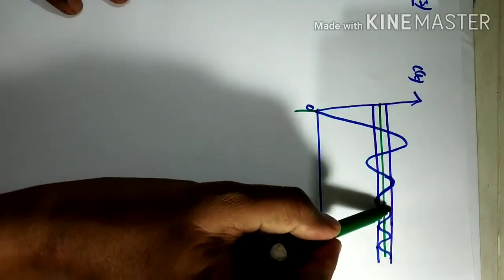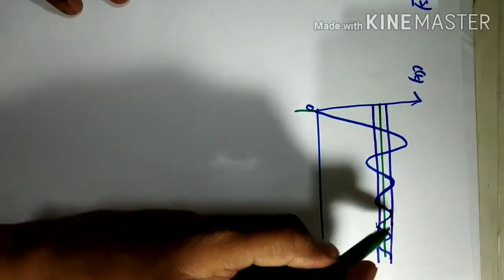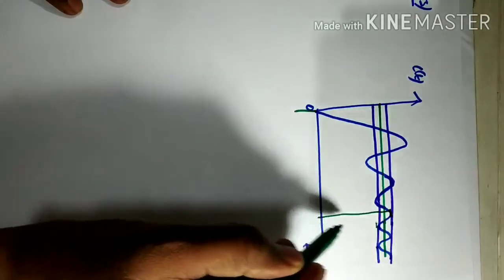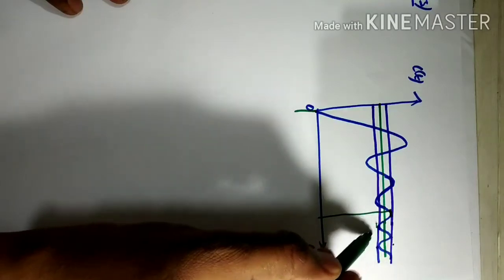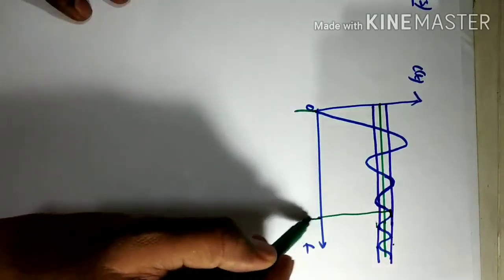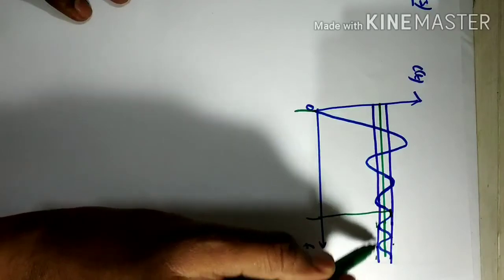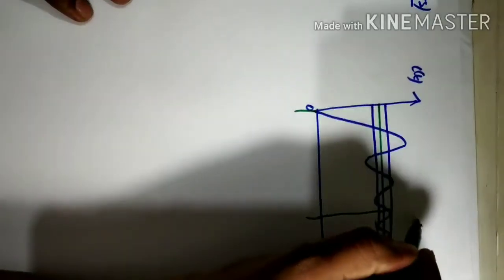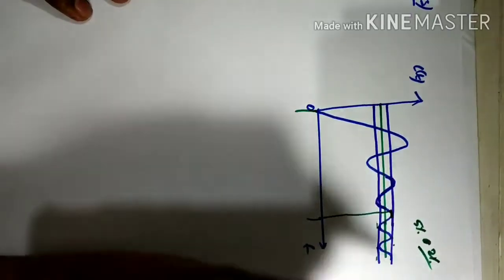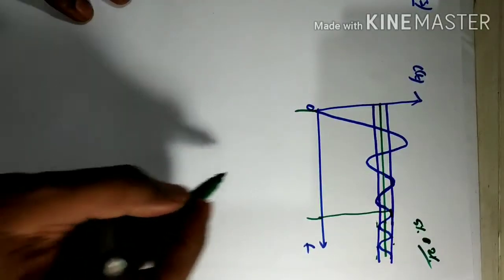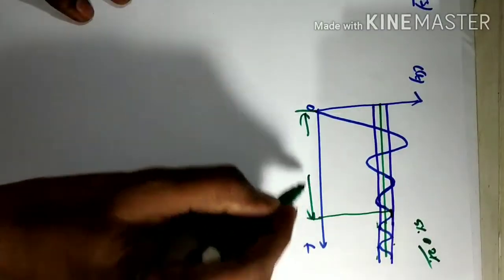Okay, this point and this point. From here, it is not going above this line, and here also the peaks are not going below. So this is settling time. It stayed within the specified error. You know that for the specified error, 5% or 2% is acceptable. Okay, so this is the settling time.